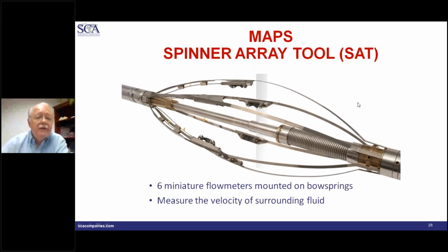What I'm showing is the next tool, and the most recent to have been developed. This is from Sondex. Sondex is now a GE company, and it's also associated with Baker Hughes. What you have here is a tool that is part of what Sondex refers to as the MAPS, M-A-P-S system. That MAPS system, if you look very carefully here, has a series of 6 individual centralizer arms. These centralizer arms are not strong. They don't hold the tool up. If I were to put it on the table, the tool mandrel would fall right down to the table. The tool housing would fall to the table.